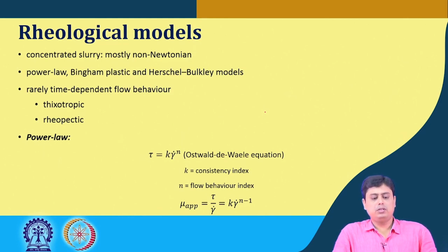We will not go into these details because I assume you know this terminology and these models. We will have an overview of the power law and the Bingham plastic, and how we predict pressure drop for slurries that exhibit power law and Bingham plastic behavior. So we will mainly focus on these two categories.